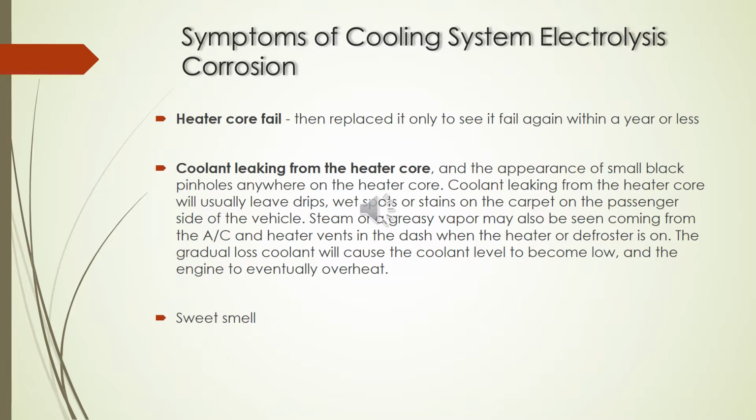Now we are addressing the symptoms of cooling system electrolysis corrosion. Number one is the failure of the heater core, and one of the things that happens is when you replace it, you see it failing again within a year or less.